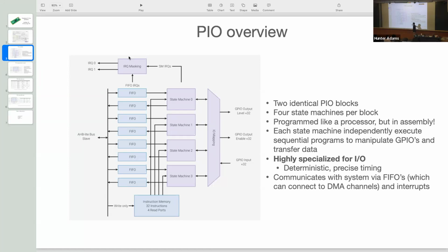With these, let's say 2 SPI channels weren't enough for you. You just build yourself a bunch more out of PIO. You write your own SPI driver that looks to your application code like just another SPI peripheral. So if you need a third, you build a third. If you need a fourth, you build a fourth. If you need another UART channel, you build yourself a UART channel. We'll look at all of these as examples, by the way.